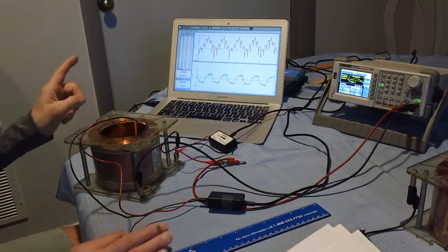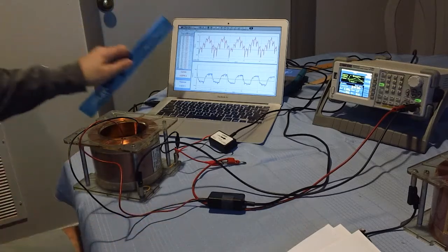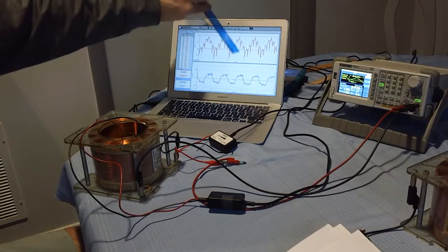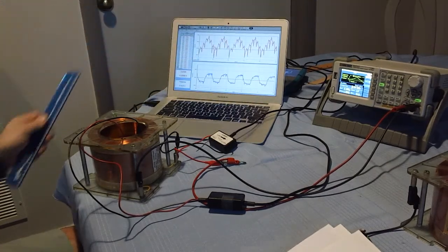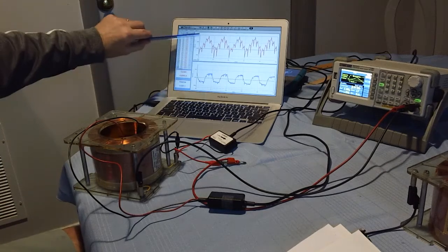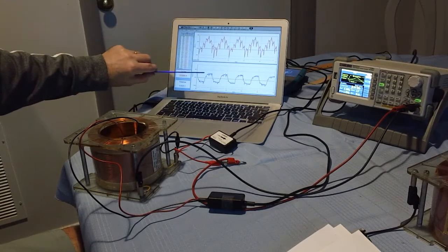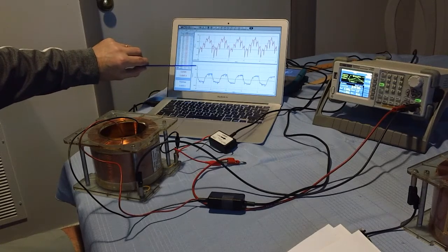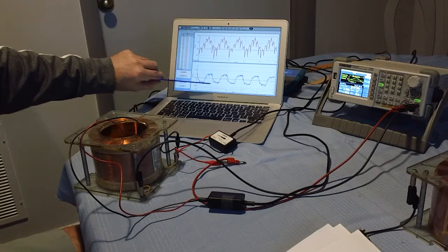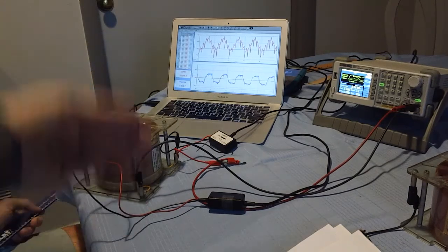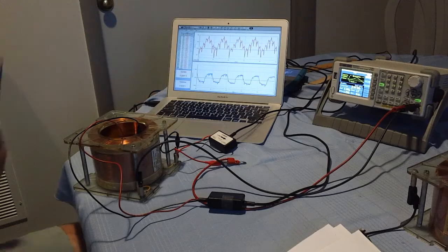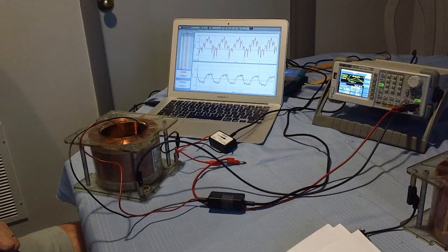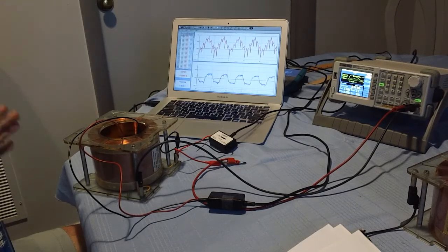All right, and what you should notice, as noisy as it is, I have an upward current here, and then I've got it ramping down here, and ramping up, ramping down, ramping up, ramping down. And every place the current is changing, I see a constant electromotive force. When it's coming down, I have a positive electromotive force. When it comes up, I have a negative electromotive force, and it's almost like a little sawtooth for the electromotive force, which is generated as the rate of change of the current going to the outer coil takes place.